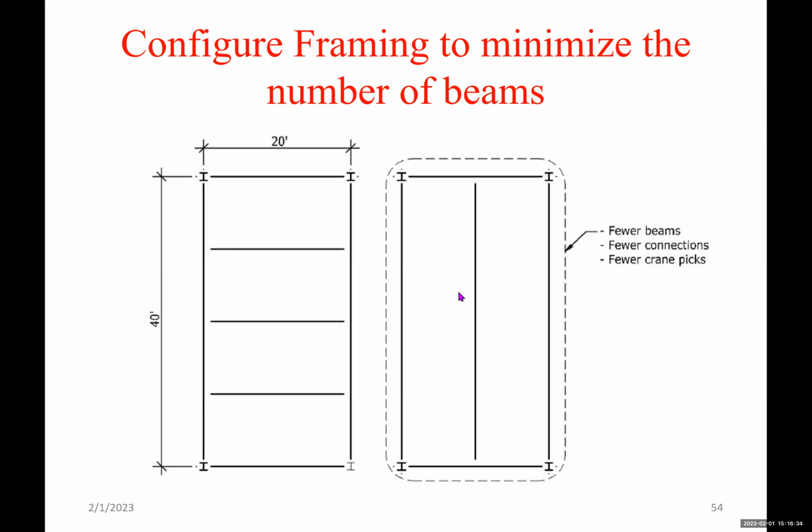I talked about that when I said we can have a schematic for the gusset plate and the member together, and have symbols A, B, C, D, and then show the dimensions A, B, C, D of the geometry. So even if it's designed by the fabricator, try to create the geometry or visualize the geometry to see if this is doable or not.